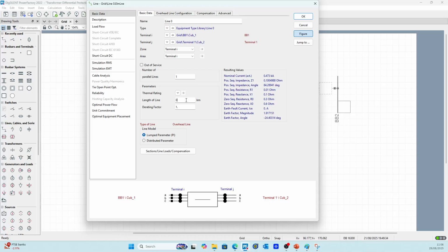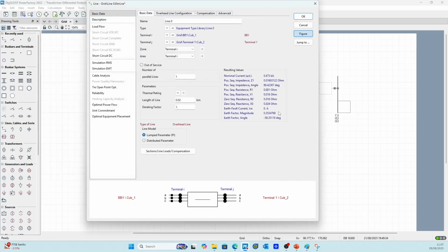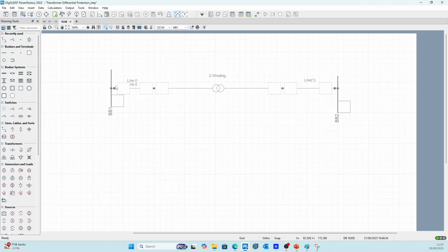Okay, see, it's very short. I can increase this one, no problem. Maybe 0.8, maybe this is now okay, that's fine, I can leave it as it is. Maybe 1.2, maybe 7, it doesn't matter. Okay, just for a sample now. So now we have almost 0.01 ohm. Okay, it's a very short cable, usually used to connect the transformer to the bus bar or to the tower basically.